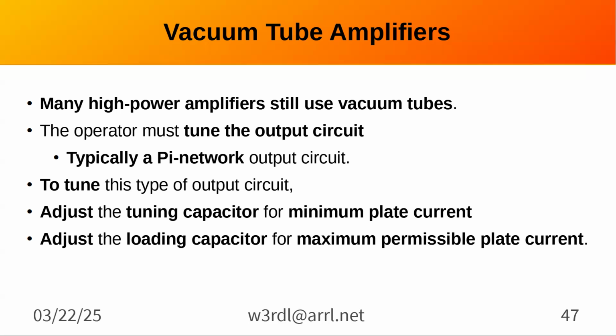Yeah. But with a tube amplifier, you're going to step down more than likely, because for 100 watts, you need 70.7 volts into 50 ohms. And if you're running on 13.8, you've got to step it up to get 70 volts. Okay, let's move on. That's back day one lesson there.